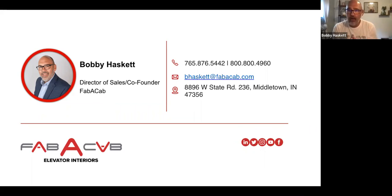There's a few of us out here in the industry that do that. I always recommend going with a company that has interlocking clips because there's a couple things that it's going to save you from. When you have a badly dented shell, if you're using an aluminum clip that interlocks with the panel below it and allows you to screw to the wall, it is much more forgiving, Eddie, than using just a panel and screwing the panel right to the wall. And we've seen that many times before.